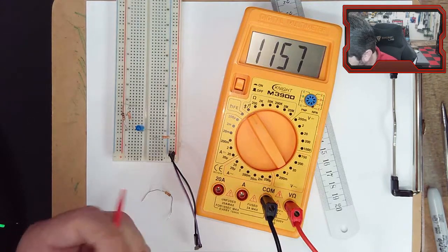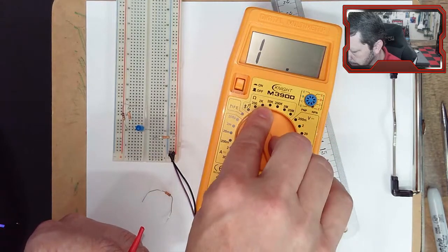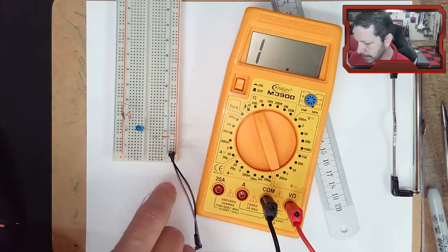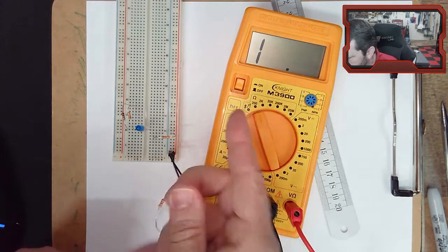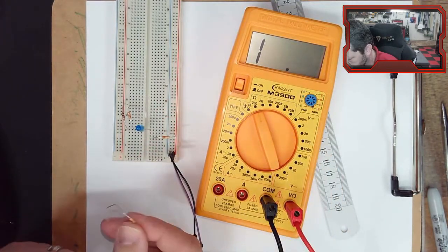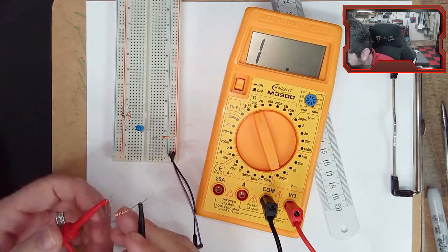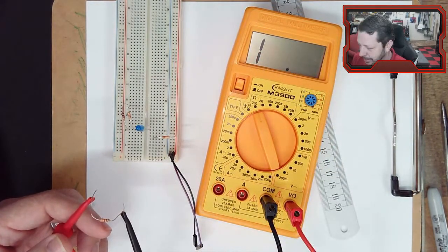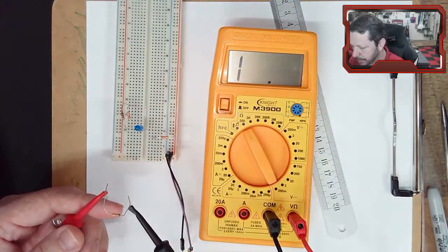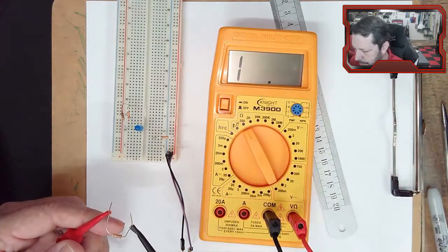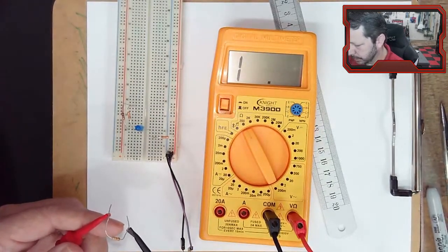It's okay. And then do I want to measure something in the 200 or less ohm range, the 2000 or less, the 20,000? So the goal is you need to know something about what you're trying to measure with one of these. So if I tried 200 and this is a 1,000 ohm resistor, let's see what happens. It just gives me 1. So I know this isn't a 1 ohm resistor. Usually whenever you get a 1 or a 0L or something like that, it's over the limit. This one just displays a 1 whenever it's over the limit.